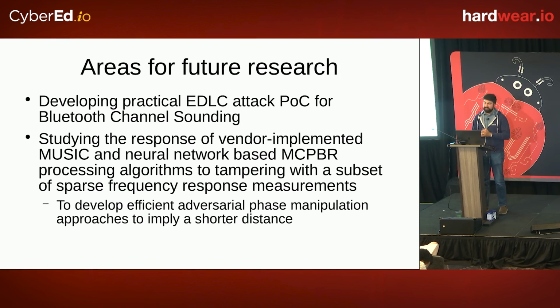There are some interesting areas for future research. One is actually implementing the phase-based ranging attacks. In principle, it should be fully doable. In practice, some of the challenges are precisely timing when you're injecting your interference, as well as putting out the correct signal phase for interference, given there's unpredictability in the phase of each of the oscillators at the different frequencies. So it's something I want to experiment with some more, and I'm working on.